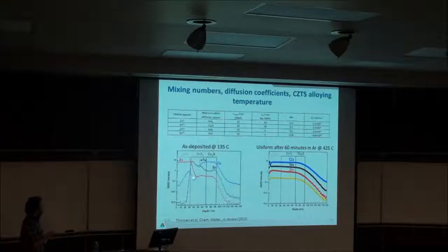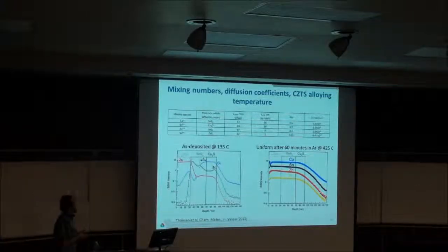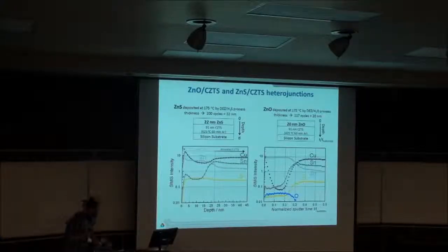So we basically determined these diffusion coefficients by doing these slopes. These lines, this is a semi-log plot. These lines are diffusion length, and in the case between tin sulfide and copper sulfide, our diffusion length was this delta, which is basically the shift between expected interface position and measured interface position. The diffusion coefficients appear to be not really huge, but the time needed for ALD growth of these materials basically brings you to very much mixed metal sulfide binaries. Okay, I'm going to skip this.